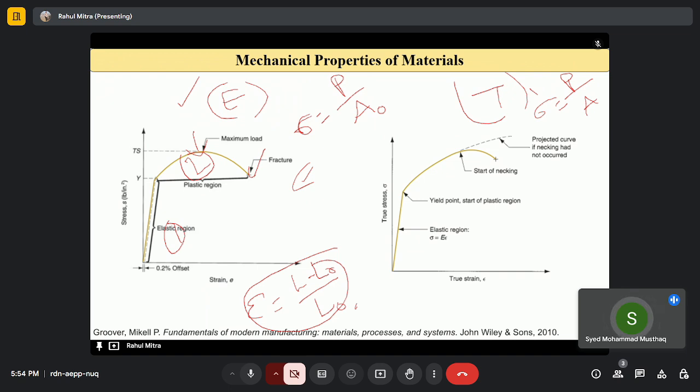The yield point marks the transition from the elastic region to the plastic region. After applying a load, we keep on increasing it. We have strain hardening of the material, because for a given strain we have to apply more stress. The maximum hardening is reached at the ultimate tensile strength, which is called UTS. After that, if we apply more stress, the material breaks, and we finally have a fracture point, and ductility measures the fracture strain, right?